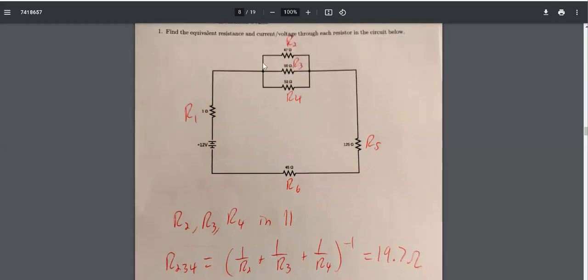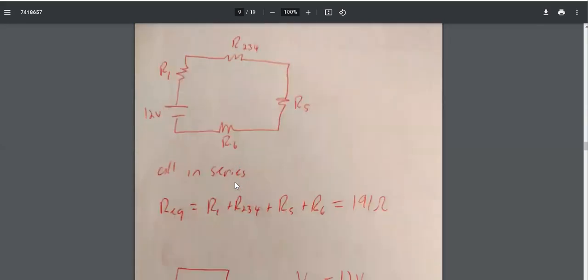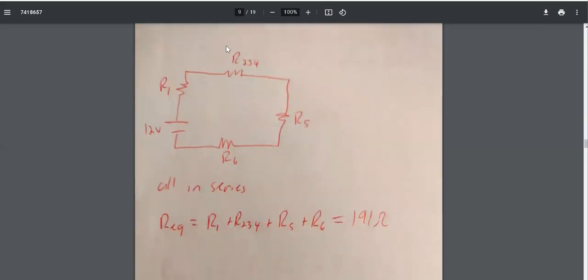And so just like before, now I redraw the circuit here, but instead of having all of these, I replace them with just one. And I don't want to leave any part of the circuit bare with nothing across it at all. So the only way to redraw it is like this, by replacing all three of those with one and not leaving any section of wire between a junction just empty.